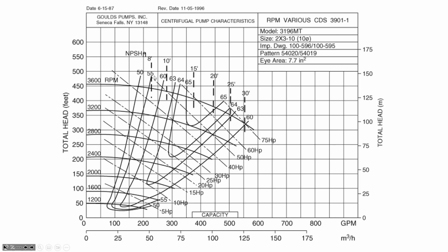It's efficiency. A certain pump is not going to have the same efficiency across a large range of operating characteristics. For example, if we have a pump that we're driving at 3,200 RPM, and it is pumping a flow rate of 160 gallons per minute, then it's intersecting here, you can see the 50% efficiency.